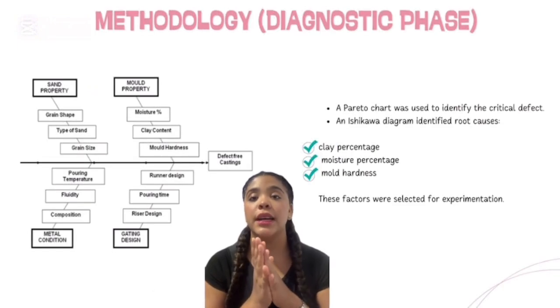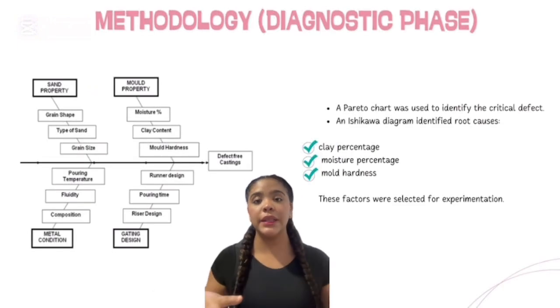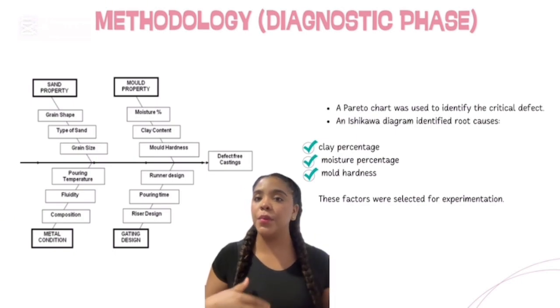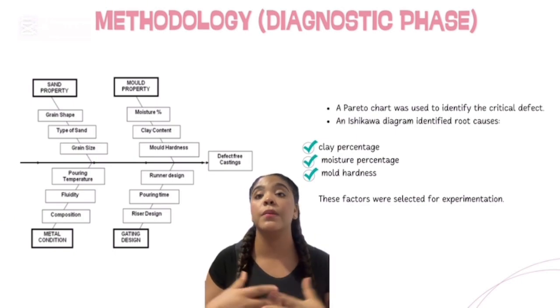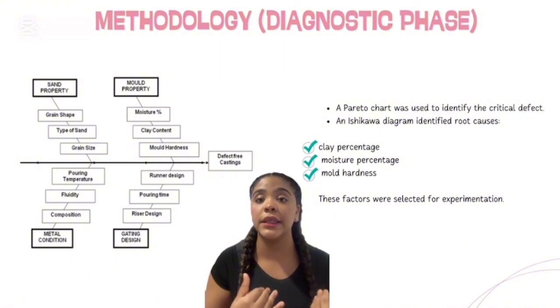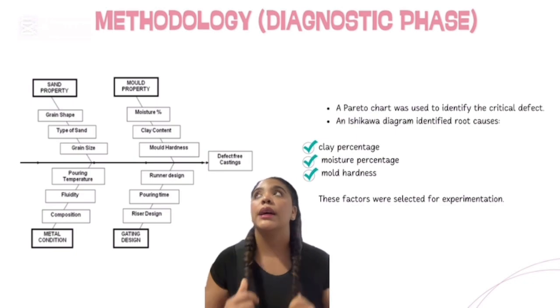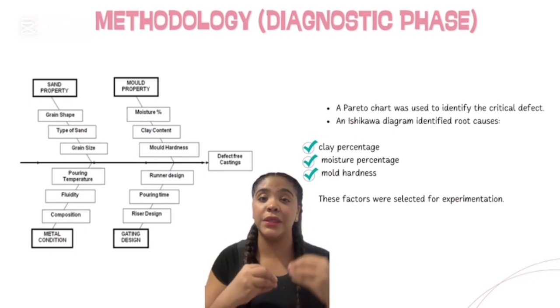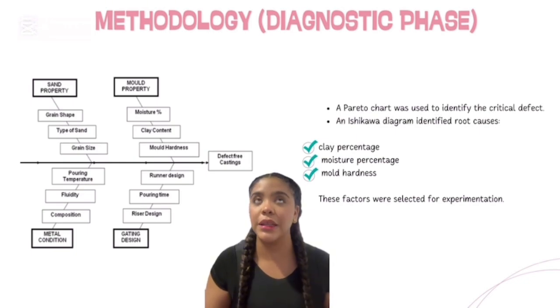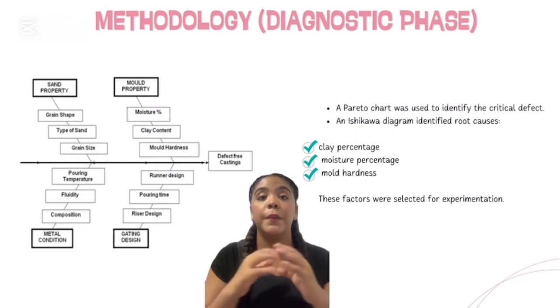They studied the actual situation in the company and defined the quality problem. The researchers collected production data from a 6-month period. Using this information, they constructed a Pareto chart which allowed them to identify the most frequent defects in the manufactured impellers.